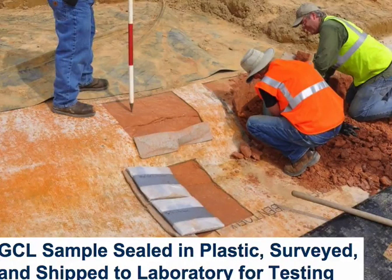And there's a little bit of extra earthwork you can see on this photo. Here we're also taking undisturbed soil samples of the subgrade that underlaid this location to look both at the geosynthetic clay liner, but also the condition of the underlying material. And as part of this process, you can take samples of the upper geosynthetics as well.